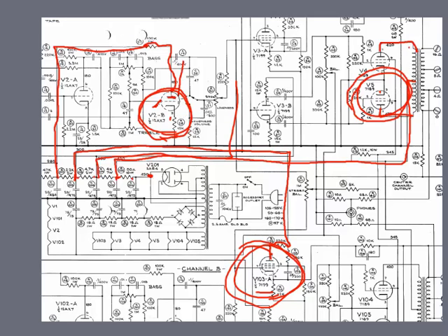They'll tell you how much current can flow through this tube without causing damage. Ultimately, you change this resistor right here to control how much current flows through that. That's a cathode biased resistor. We'll talk more about that later. But you see how these basic principles of voltage dividers are used throughout these amplifiers to get different voltages at different places because of the requirements of the circuits that they're building upon.